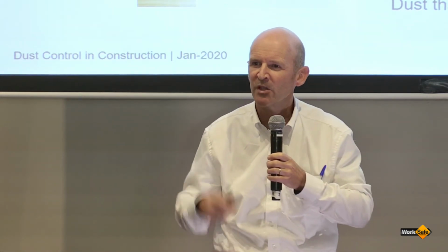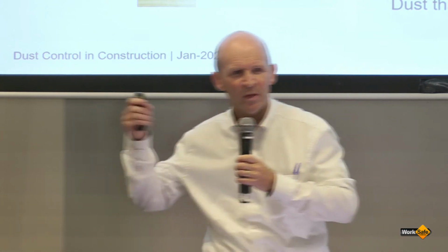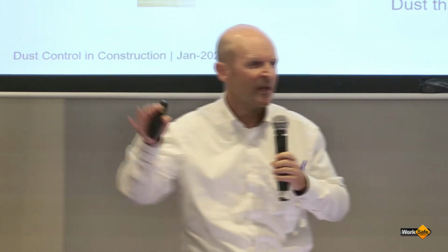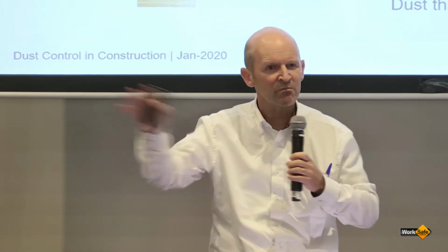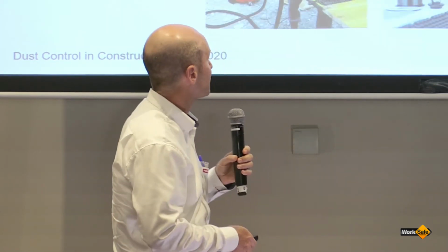Well, that's really important. So you can be working all day, and you think you put your tool down, and the dust is just miraculously going to disappear. It actually takes some time for it to eventually settle. So most of the time on an active building site, you are generally exposed to respirable crystalline silica dust particles.